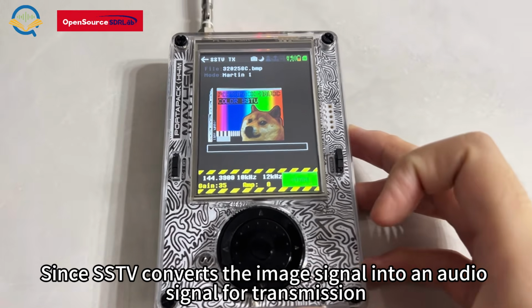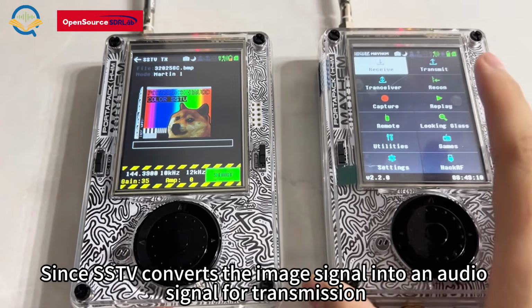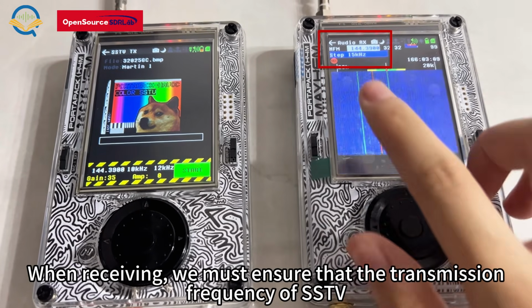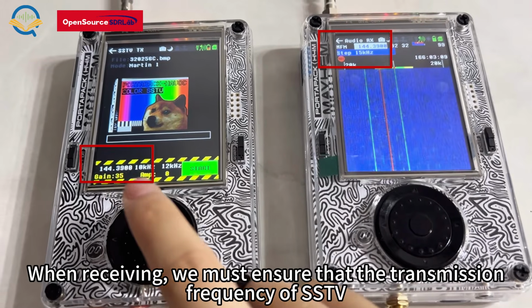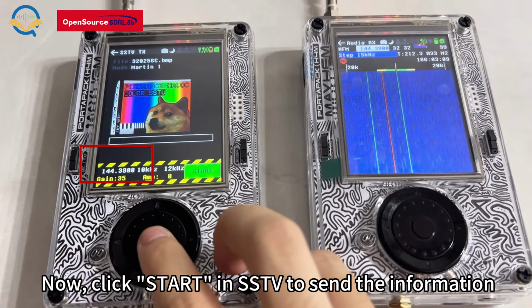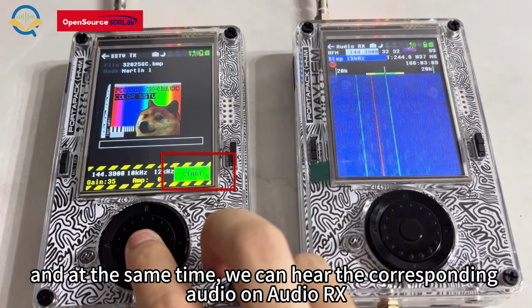Since SSTV converts the image signal into an audio signal for transmission, we can use the audio application to receive the signal. When receiving, we must ensure that the transmission frequency of SSTV is consistent with the reception frequency of audio RX. Now, click Start in SSTV to send the information, and at the same time, we can hear the corresponding audio on audio RX.